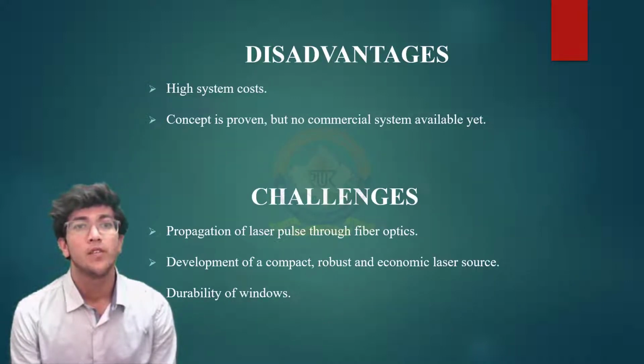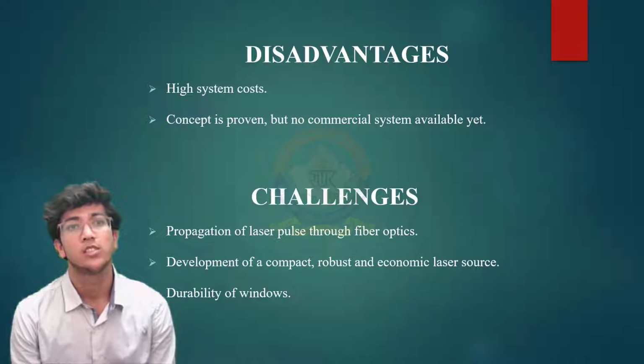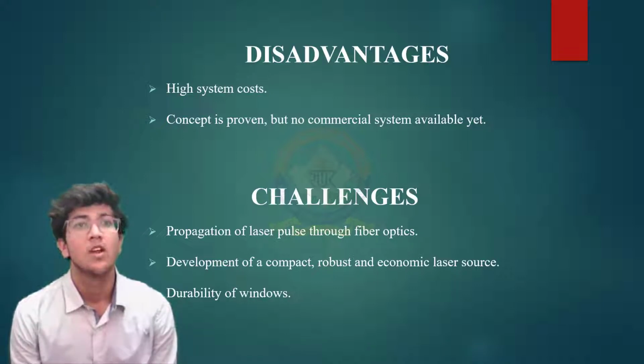There are two main disadvantages of the laser ignition system. One is high system cost. This system is very expensive because of the complex manufacturing of the laser spark plug. The concept is proven, but no commercial system is available yet. As we can see from the above slides, the laser ignition system is very much beneficial compared to the conventional spark plug, but there is still no commercial use of the system. The challenges are propagation of the laser pulse through fiber optics, development of a compact, robust and economic laser source, and durability of windows.